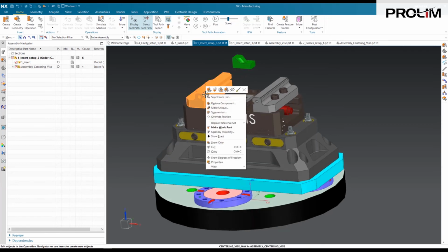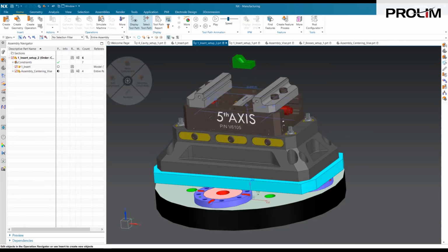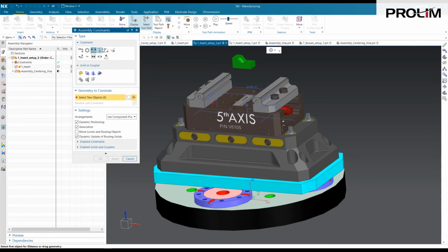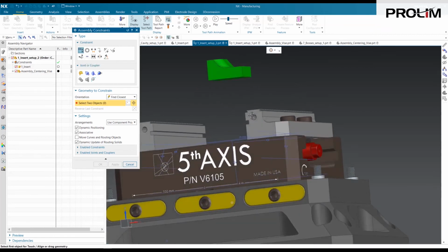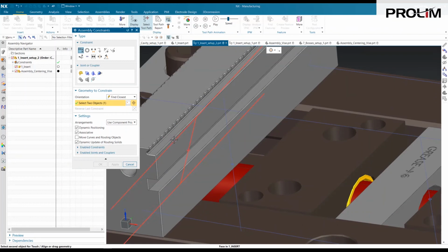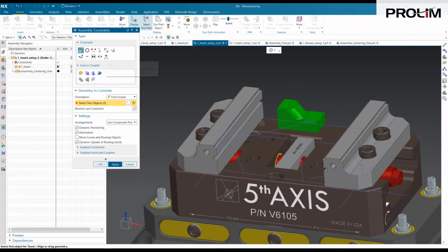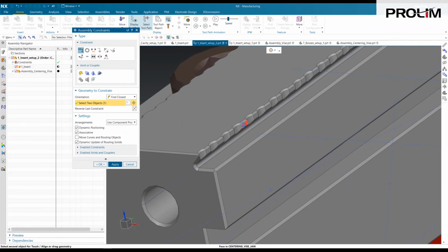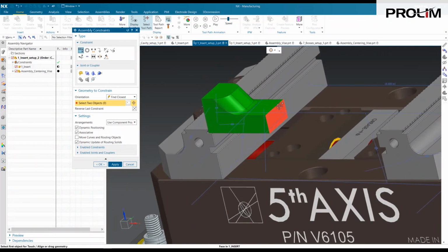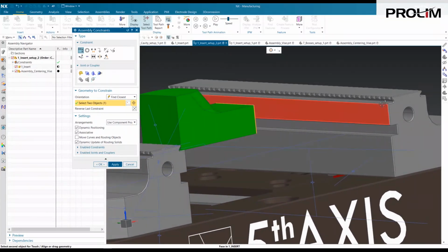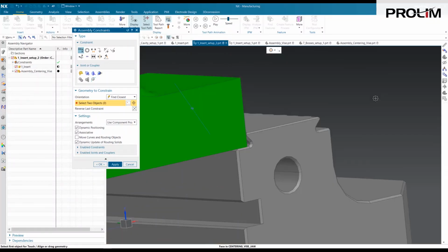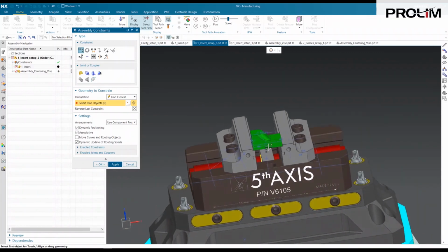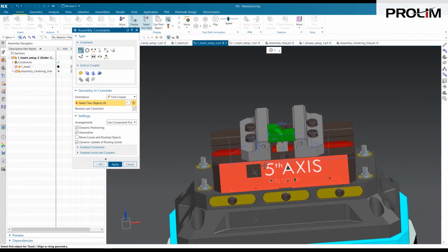All right, so right away, the first thing I want to do is just override the position in this. So on my assembly constraints now, I'll fix the base, and I'll just use touch aligns from here on out. I'll touch bottom of the part to this surface. We'll touch the side to here. And we'll use the back side of the part to touch to the gripping point of the jaw, as well with this one. And then once I select that jaw, they'll both collapse and keep it centered within the vise base.